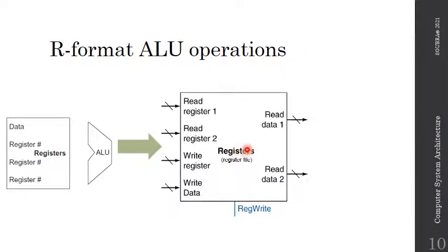And we're going to find out that this is the more detailed version of it. By the way, I really like to call the registers a register file. From now on, and it's out there in the literature as well, you're going to find something that we call a register file, and in the register file you're going to find the defined registers that are usable as defined in the ISA. In the case of MIPS, in the register file you will find 32 registers, and among them, for instance, register 0, which is hardwired, etc. Fair enough.